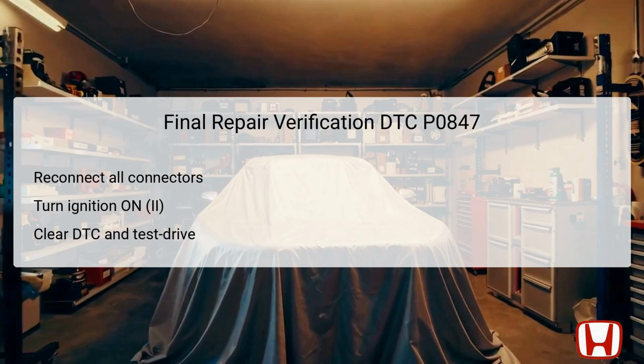Once the reconnect process is complete, the ignition must be turned to the on 2 position to activate the vehicle's electrical systems. Following this, the technician will clear the stored DTCs using the HDS, thereby resetting the monitoring system. After clearing the codes, it is essential to start the engine and allow it to reach normal operating temperature.